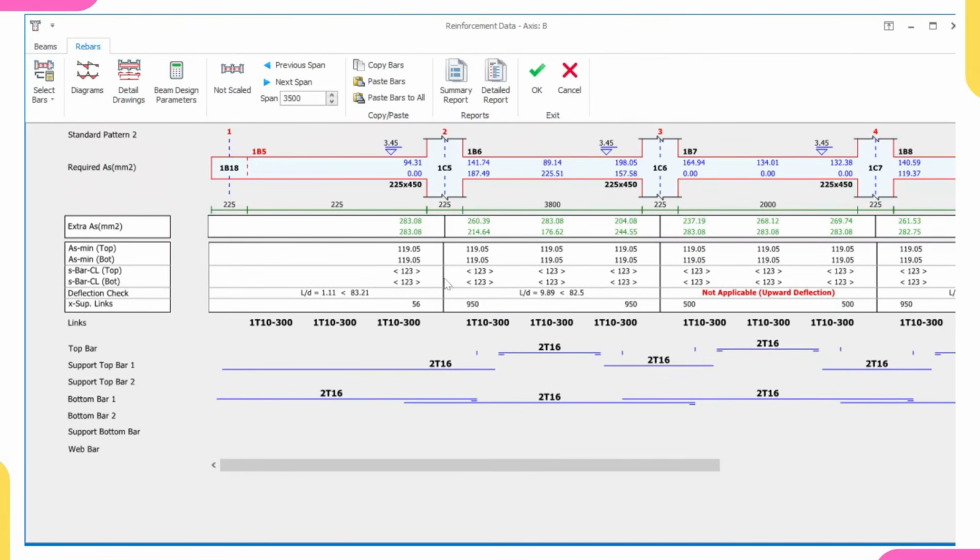If you are doing the interactive design, don't forget, if this is the area of steel required, then these ones now are the area of steel provided. This is the area of steel required. This one is the area of steel provided. I am not seeing where the utility ratio is here, because I could have explained it, but don't worry, once we go to the code room, I will explain utility ratio so that you understand.